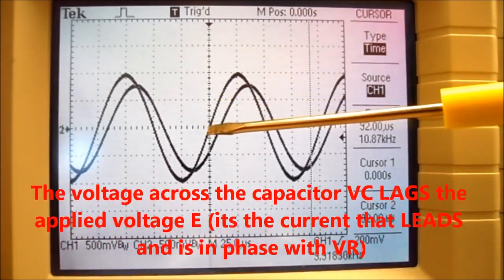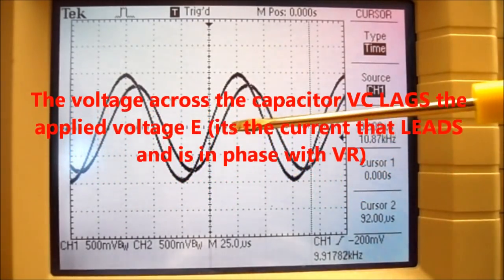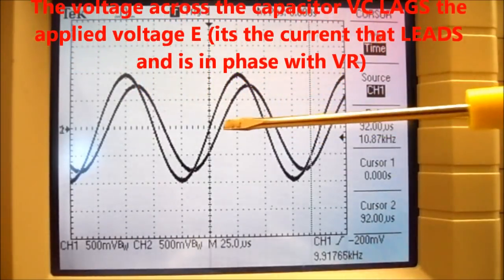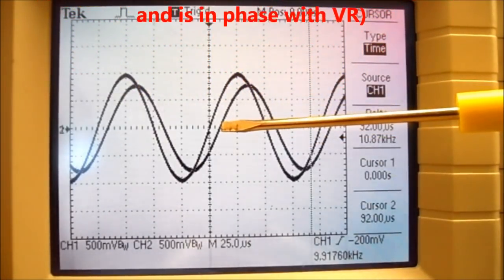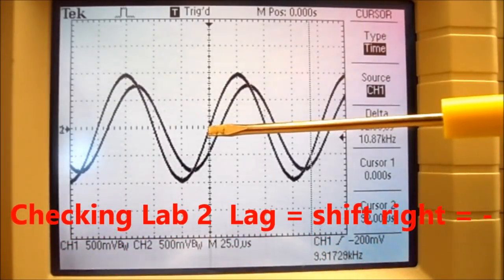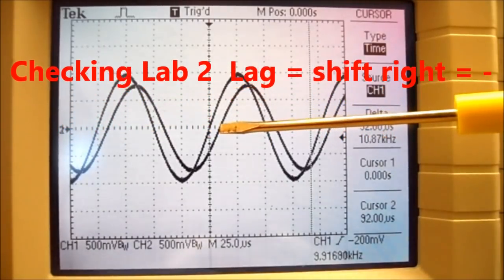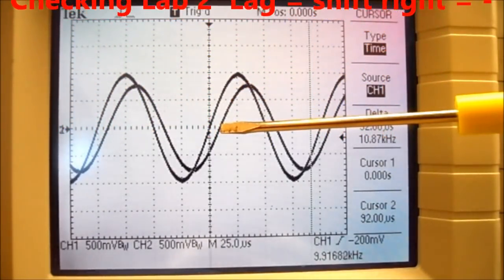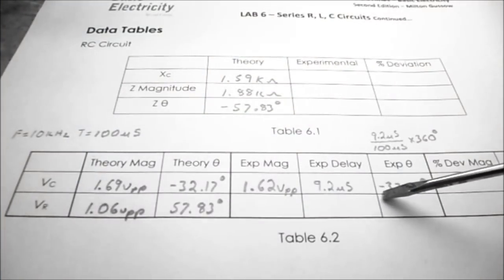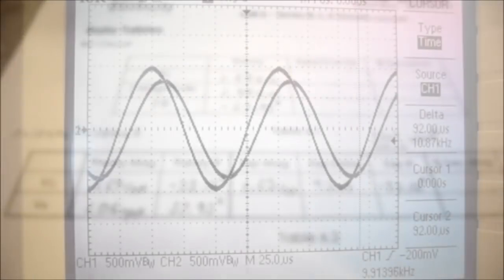So here you can see this is the input voltage, and this is the voltage across my capacitor. You can see the voltage across the capacitor lags the input voltage by so many degrees. So that's where the minus sign comes from. In table 6.2, I've put the minus sign in front of my 33.12 degrees.